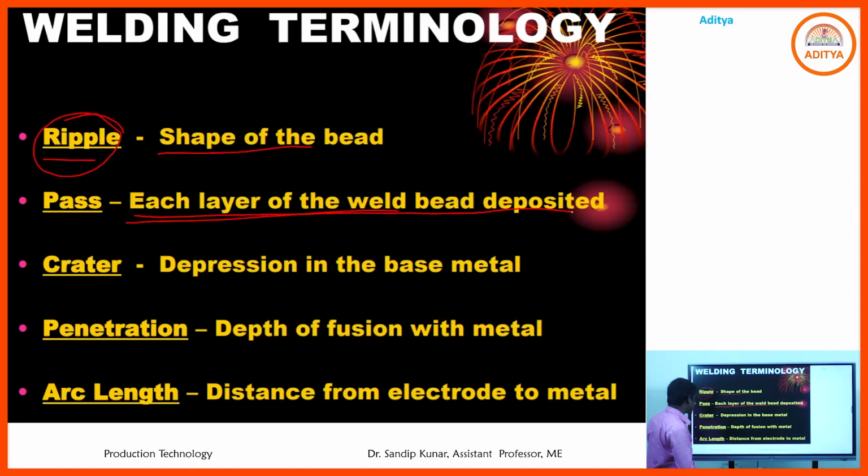Next one, crater. Crater means a depression in the base metal. When we move the welding torch, some depression is created on the weld face.